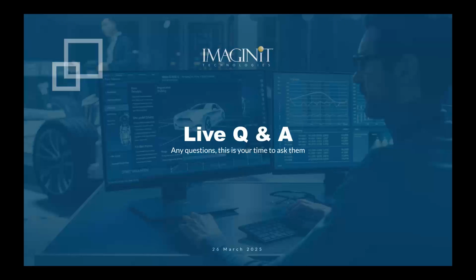XREFs, I like XREFs generally to be relative path. That way, if I make a copy of a folder and I drop it somewhere else, it's all relative path. So I don't need to go through and fix everything. I also like to set the XREF layer. There's a global command for XREF layer where you can put your XREFs all on a specific layer. And I set that in the template. Yeah, that's more or less my preferred configuration.